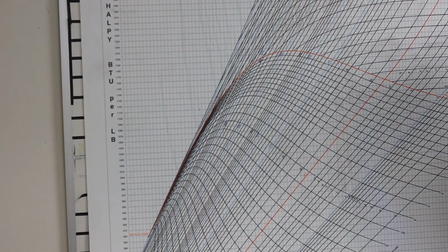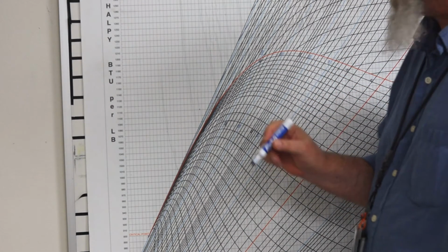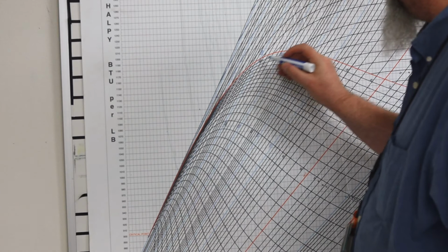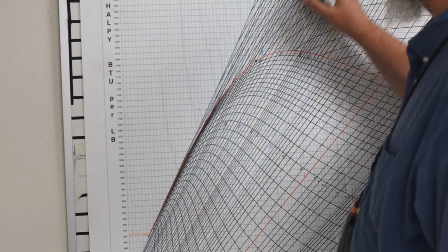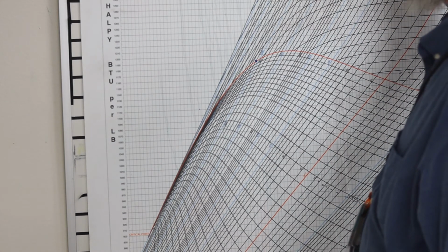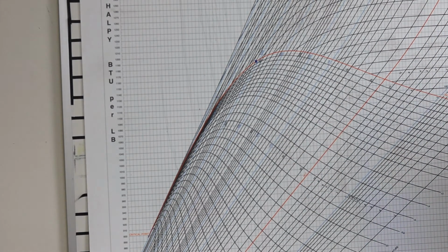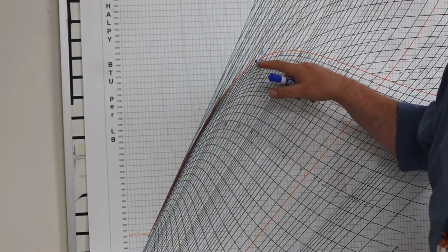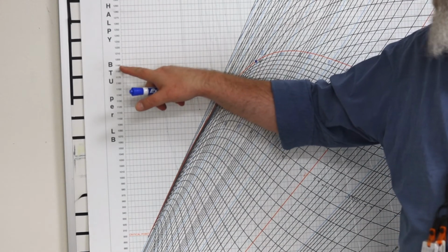So one of your questions, I gave you dry saturated steam at 1100 psia. Well, once again, it's really important that the dry saturated matters, right? Because that means we're on this red saturation line. So there's 1,000, there's 1,100. This is where we're starting. Dry saturated steam, 1,100 psia. I now know what that starting enthalpy is. It's just under 1,190 BTUs per pound mass.